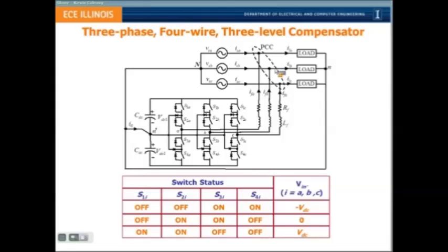And we saw the hysteresis control for a two-level inverter has the drawbacks of wide switching frequency variation. It's aperiodic switching, and the switching frequency variation is quite huge. So we just look at whether, if multi-level inverters are used, we would be able to get any advantage. This is a three-level inverter.